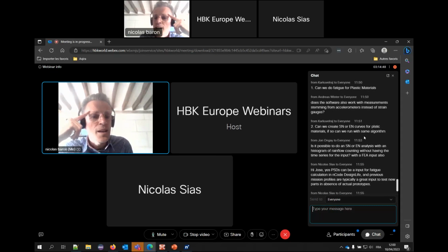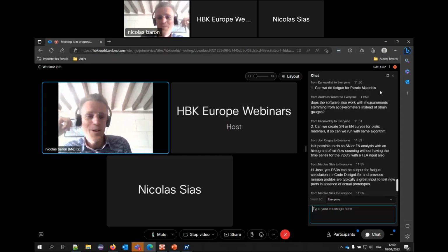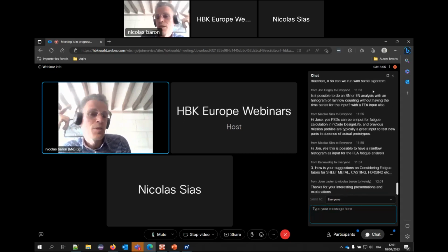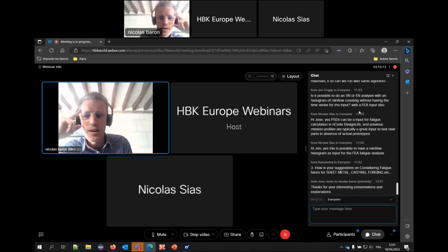Can we do fatigue for plastic materials? Yes, you can. No limitation in theory. The hardest thing for plastics, however, will be the curve characterization, the strain life curves that we talked so much about today extensively. They are usually harder for plastics, so that will be one of the main limitations. But in theory, there is nothing preventing you from doing calculations with plastic parts, even if, as I said, in real life it might be a bit harder.